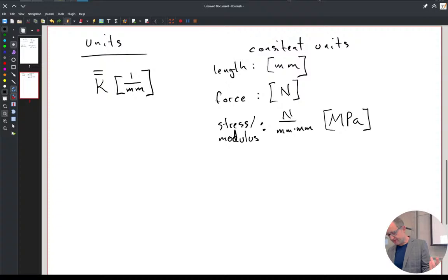These are the units that I like to use in FEA in general, newtons and millimeters. So I'm not defining, all right, this little part that I have that is 3 centimeters long is 0.03, and then I have to plug in gigapascal as 10 to the 9 values. Megapascal is nice. I know ANSYS likes to try to take care of the units for you, but in the background, the FEA doesn't care what units you're using. It can be all unitless if you want.